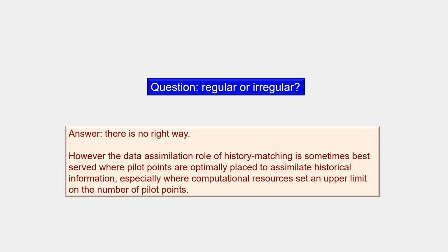And if I've got a multi-layer model and I have different sets of pilot points for each layer, and each one of those pilot points is used for interpolation of different parameters, then I am going to have to be economical about how I emplace them, because I could end up using too many pilot points for the computing resources I've got, and then calculation of the Jacobian matrix could become very numerically intensive.